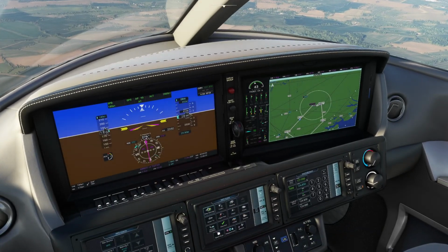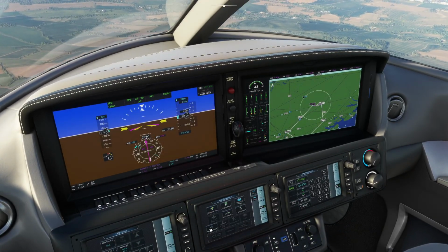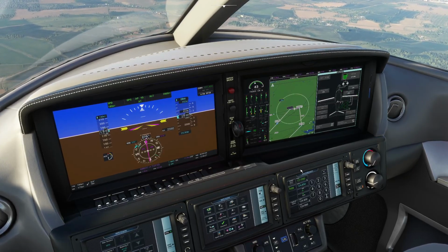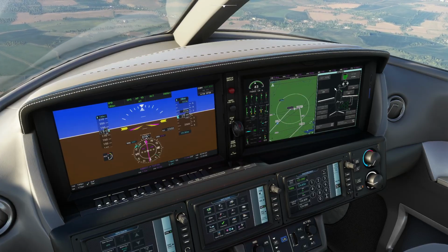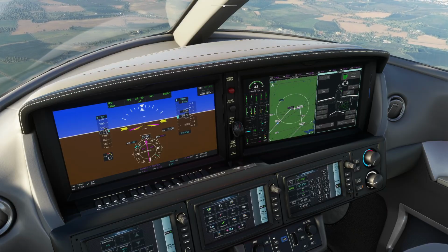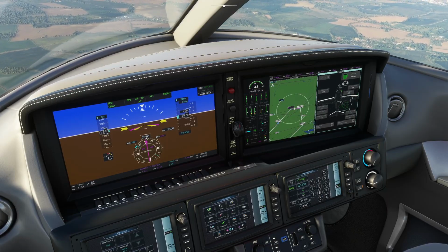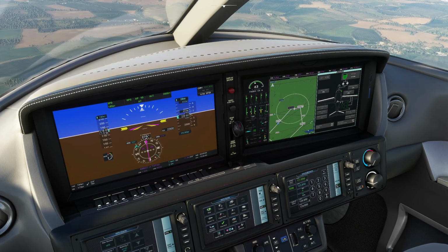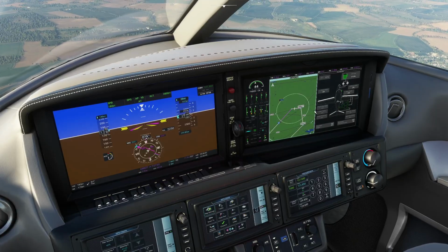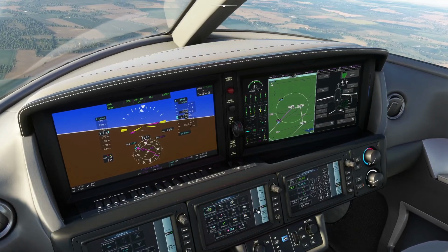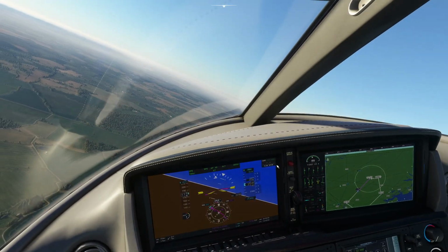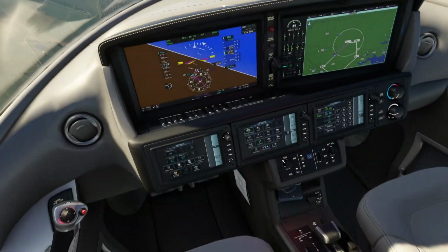If we go and have a look on that aircraft systems page, pull up ice protection, we can see there's minus 1, minus 2. So if you remember, to be able to get rid of this, what we need to do is switch the focus. I'm trying to remember how I did it now. There we go. It's this one. So you roll the outer ring if you've got multiple panels displayed. You get the focus back on the left-hand one, and then you can say full, and it will make it go back to full. Okay, so we're turning back towards the runway, so we can go for heading mode now.